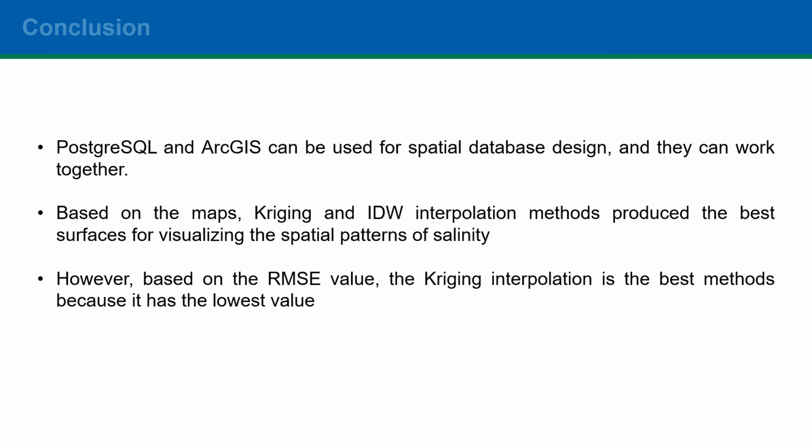Based on the maps, I concluded that the Kriging and IDW interpolation methods produce the best surfaces for visualizing the spatial patterns of salinity, and both maps were almost identical. However, based on the root mean square values, the Kriging interpolation method is the best method because it showed the lowest RMSE value compared to IDW.